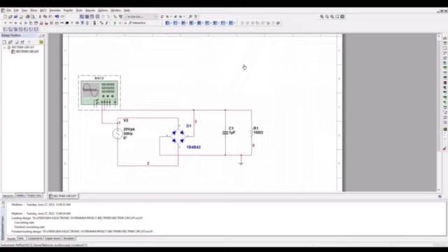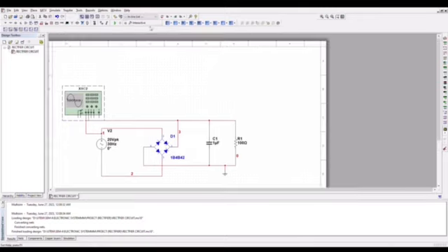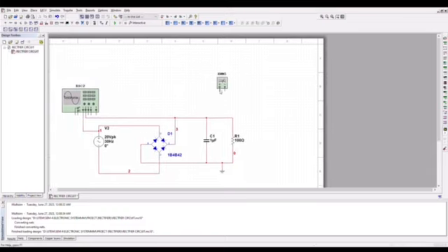the voltage peak to peak is 20 volt for channel 1, and then the channel 2 voltage peak to peak is 18.1 volt. Then we measure the current for DC. You can see here, this is the IDC value, 59.217 milliamp.